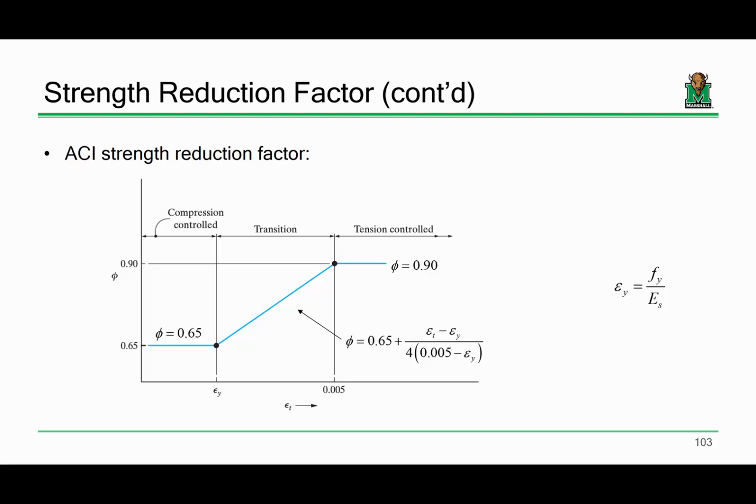I'm not seeing that. Okay, so here's the thing about steel. Steel is a material that is very, very ductile. It can withstand deflections far beyond yielding. Okay, so do you remember? I don't know if I showed you all in this class, but I think I showed you in steel design. Do you remember me talking about the football field analogy? How up until yielding, that's basically the 1 yard line, and then everything past that's the rest of the field. Steel has a remarkable ability to withstand deflections far beyond yielding.